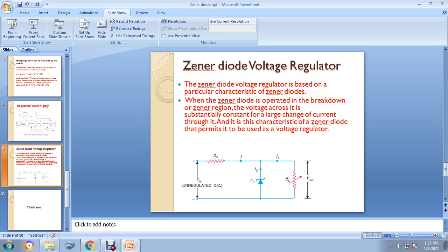It means the Zener diode is used in its reverse bias region, as you all already know. Under the reverse bias condition, the current through the diode is very small, of the order of a few microamperes. When sufficient reverse bias is applied, electrical breakdown of the Zener diode occurs, so a large current flows through it. The breakdown occurs at a voltage called the breakdown voltage. Under this condition, whatever the current may be, the voltage across the Zener is constant, equal to Vz. This large current due to breakdown is limited by connecting a resistance in the circuit.